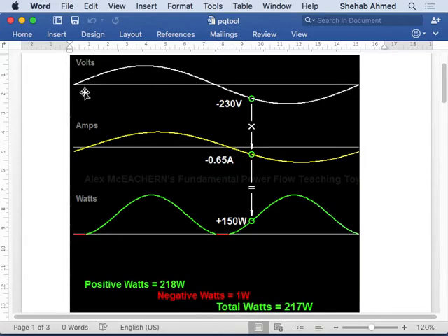This is the voltage that we have in the system. This is the current we have in the system. Okay, maybe there's some small phase angle. Negative 1 watt power, sorry. Because you adjust it, you can play with the numbers, and maybe I didn't adjust it properly. But this is pretty much resistive, right? So you ignore the negative 1 watt here. Then the current will be in phase with the voltage, and negative watt should be 0. So sorry, I should have made it purely resistive here.